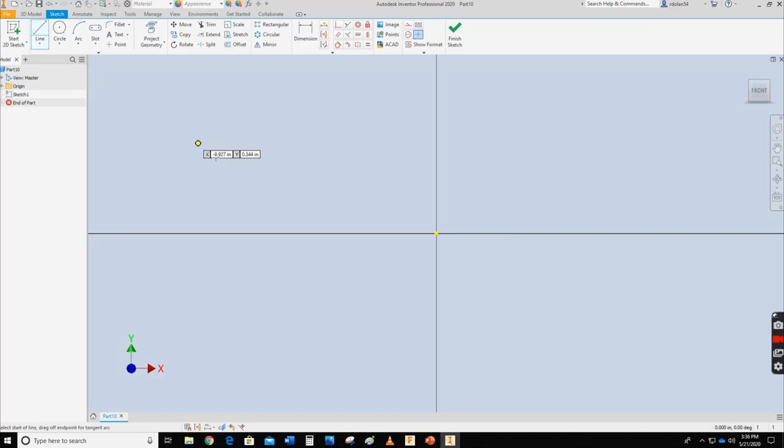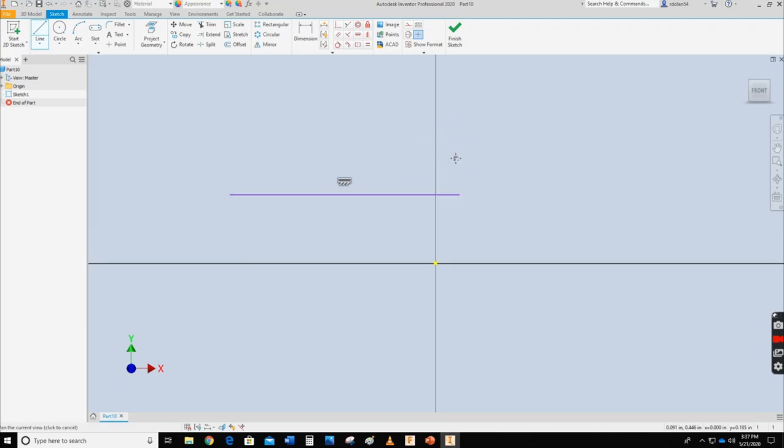Okay, we're just going to go up to a line, and I'm going to create a line here, and I'm going to drag it as I move closer and closer to 0. Once I hit 0, you'll see there that there is a little icon. That icon means that it is horizontal. You'll see it says 0 degrees, and that little icon tells us that it is horizontal. If I click on it, you'll see that now when I drag that up, I have the horizontal constraint shown, and I also have a 90-degree perpendicular constraint being created.